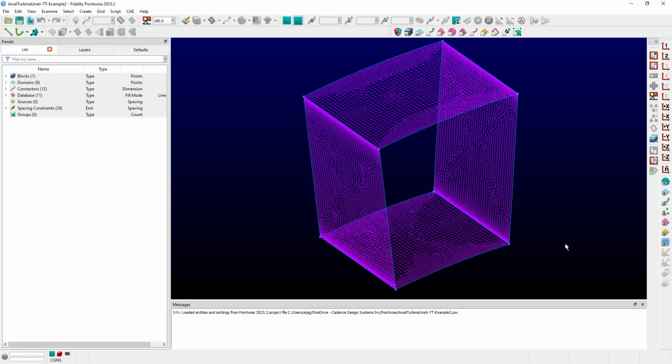Today I'd like to cover the question of enforcing periodicity in domains or surface grids in Pointwise, while at the same time using the T-Rex anisotropic method to initialize layers in an unstructured block.